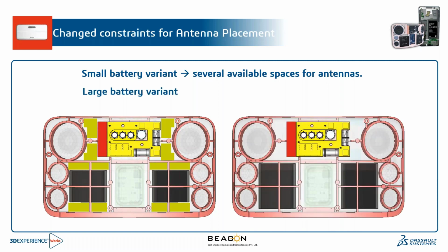So here are two cases where, from the previous to the current design, initially there were a few spaces above the batteries where we could position the antennas, but now that the battery size is large, there is one more variant added. Even for this, if we have to do the antenna design, we can make use of Antenna Magus, which is much faster since we have a set of antenna libraries available, so that we need not start from scratch.